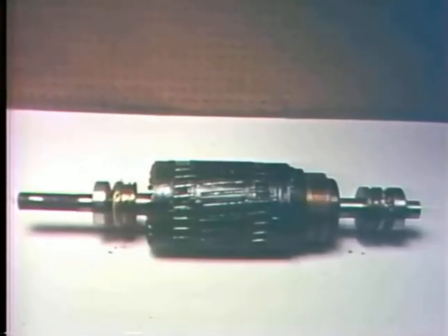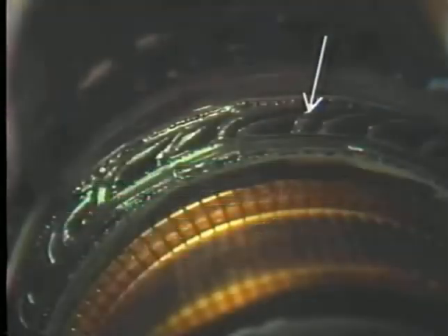The armature here is the entire rotating assembly. It's made up of the shaft, the armature core, the armature windings, and the commutator. The shaft supports the armature and allows it to turn. The core supports and houses the armature windings. These windings are the rotating, current-carrying conductors, and the commutator is the electrical connection that goes from the brushes to the windings. The actual connections to the windings are here on this section of the commutator. These points are called risers.